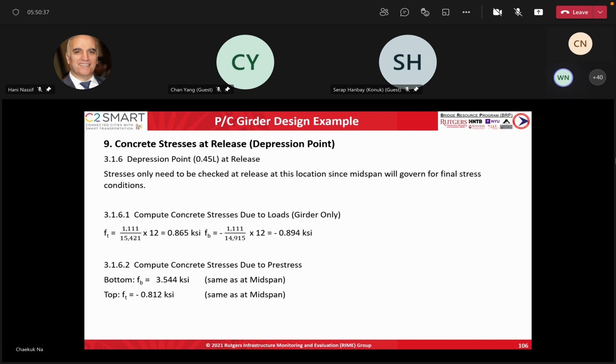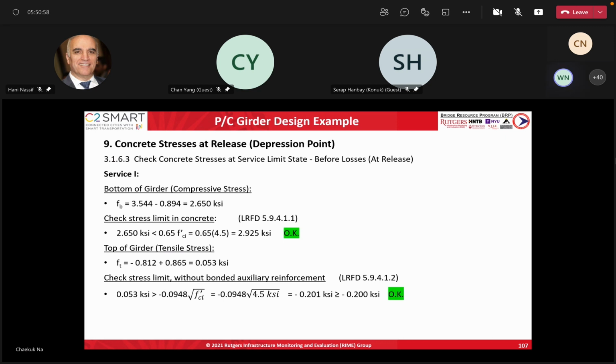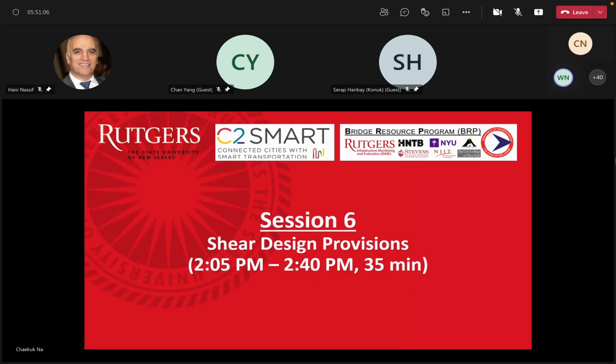So that needs to be checked because we don't want cracks at the top, nor at the bottom. So they are checked there. We make sure to have the value of the moment at that position, which is different from the WS²/8 which we used at midspan. Okay, next slide. It just goes the same way, top and bottom. Next slide. Okay. This concludes the flexural design.